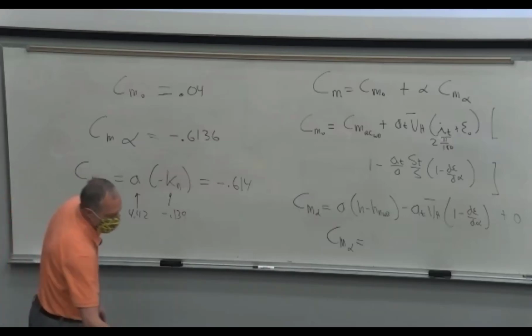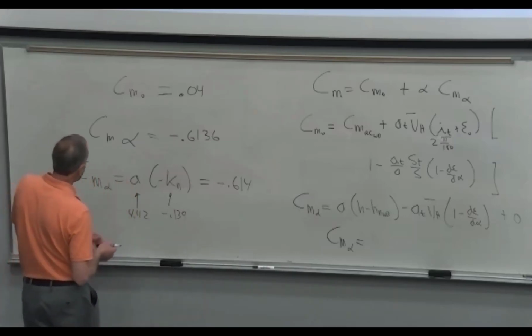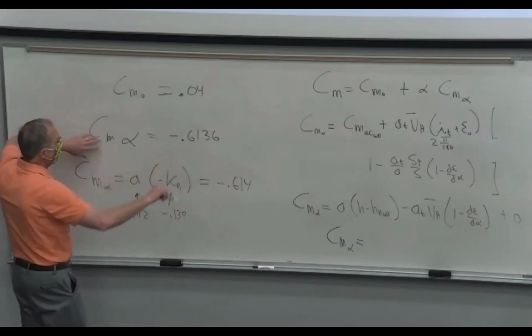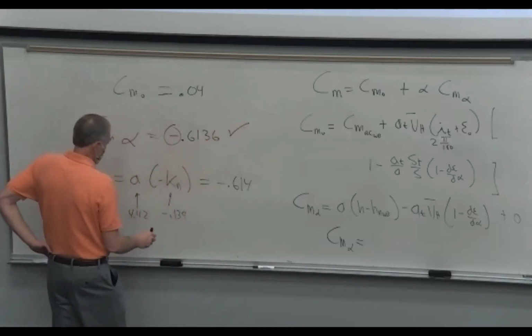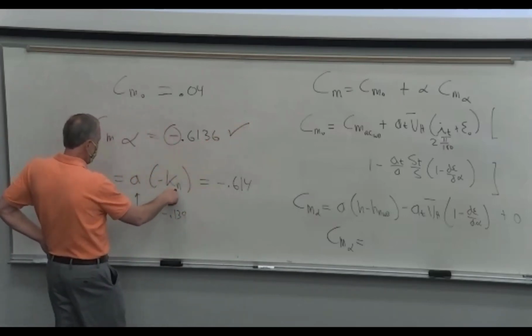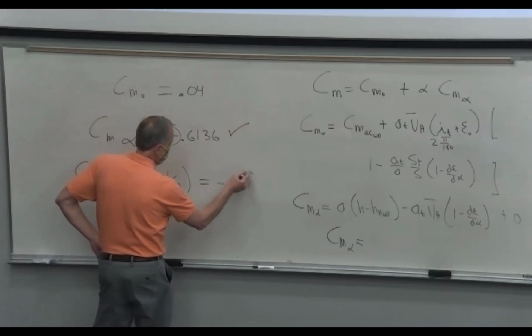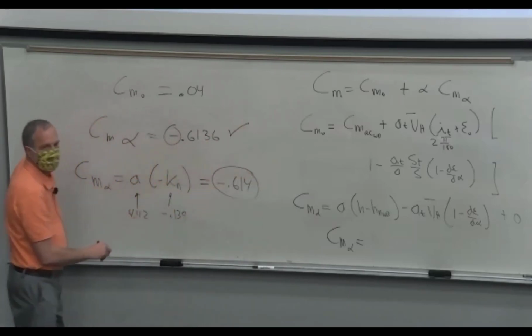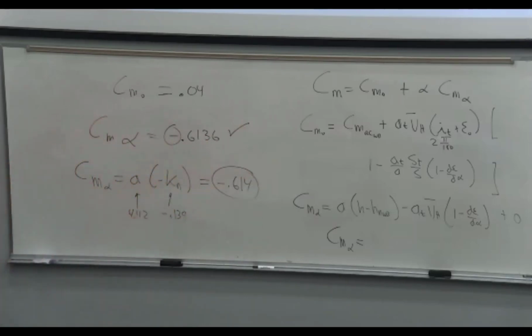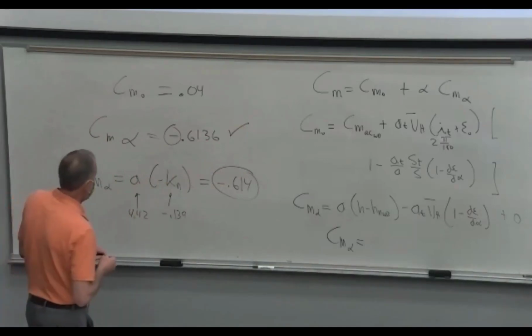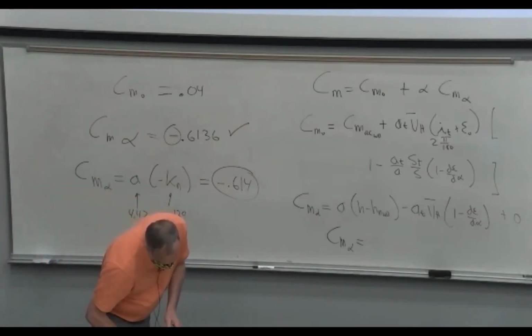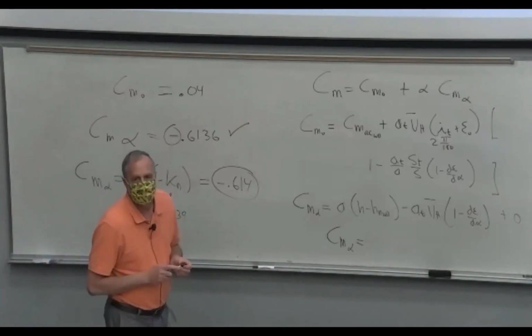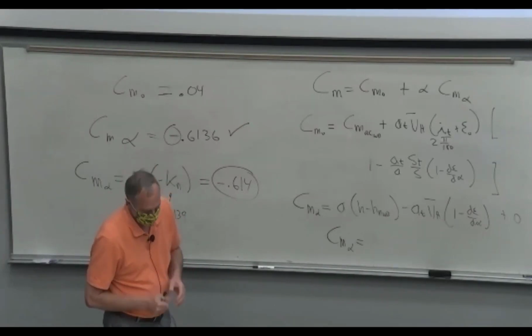So indeed, you can calculate the stability multiple ways. Calculate Cm alpha straight from the big formula. Negative, stable. We've already calculated the neutral point. You can calculate Kn and then calculate Cm alpha this way, or you can just look at the value of Kn and say, hey, it's positive, so it's stable. Either way, that static margin was a little over half a foot, right, that we need to shift the CG.